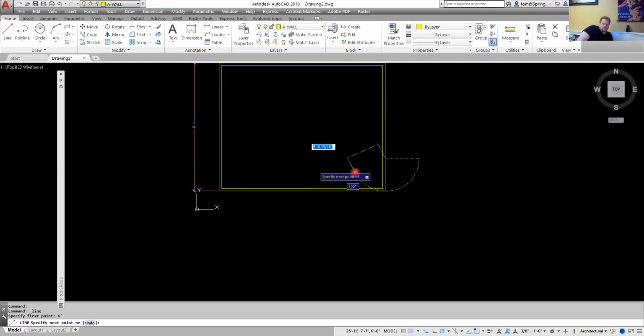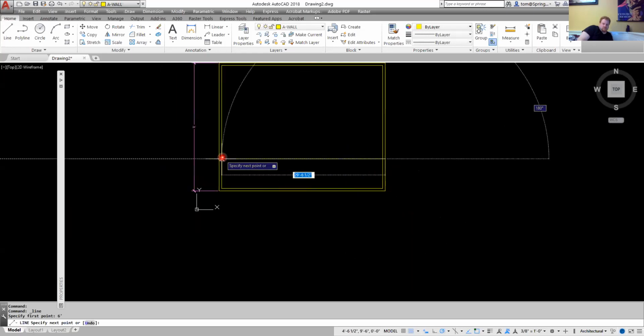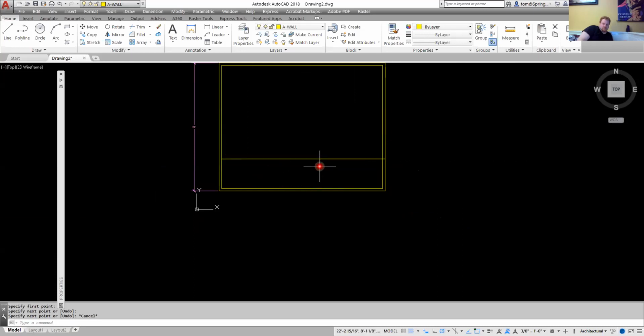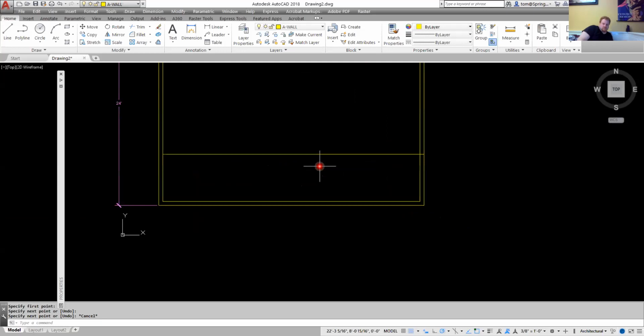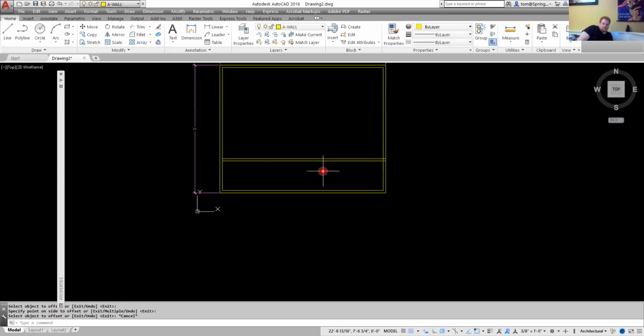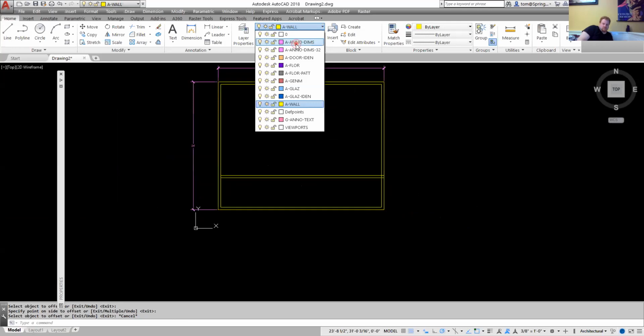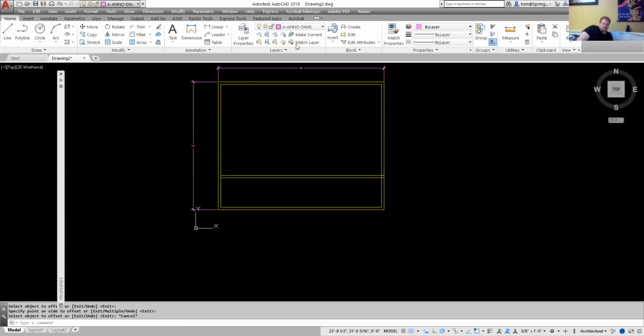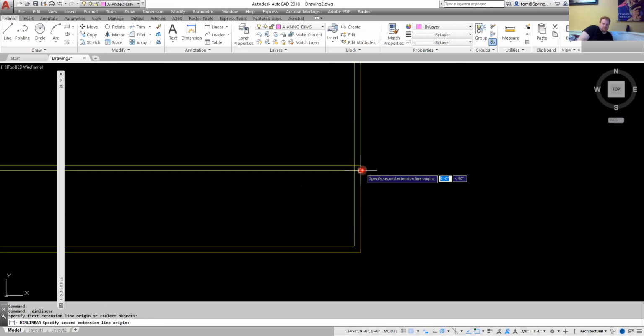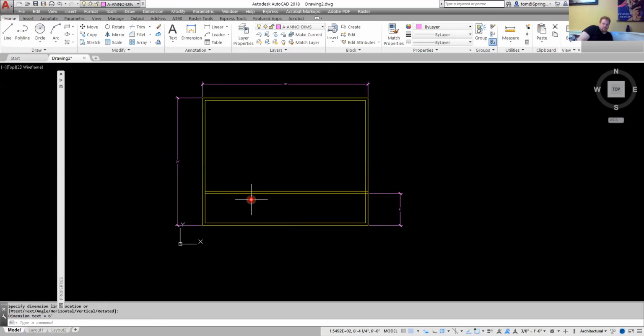And then that gives me the means to pull this all the way across and drop that there. And now I'm going to have to offset these, and these are 5 inches. So I'm going to offset this 5, boom, like that. So I've got that. Then I'll repeat to the other side. But before I do, always check your dimensions. Make sure they're accurate. So I'm going to make sure I didn't make an error. I'm going to pick this point here to this point here. It should be 6 feet if I did it right. And it is. So we're good to go there.